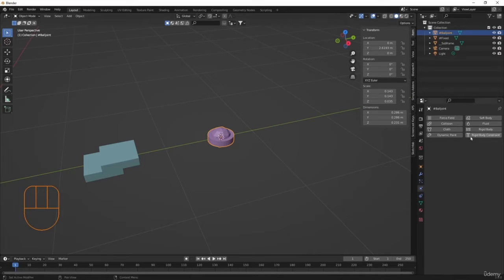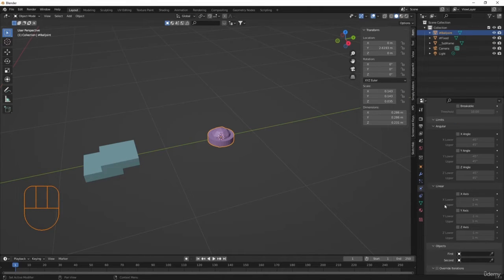And we need to make it a rigid body constraint. Now we could make it a point constraint, but I actually don't like to do that. It can cause some just weird rotational problems. I like to kind of limit the rotation. So I'm going to make it just a generic spring. I'm going to put 0 for all the linear limits. 0, 0, 0, 0, 0, 0.